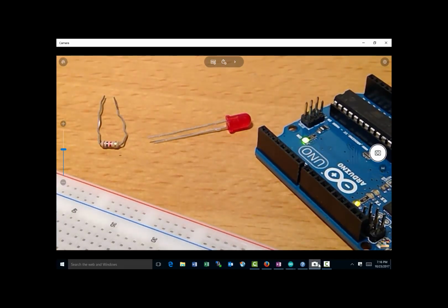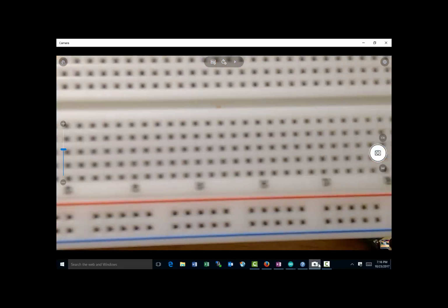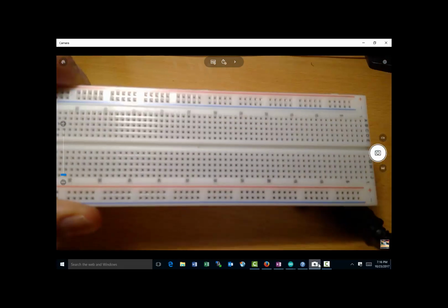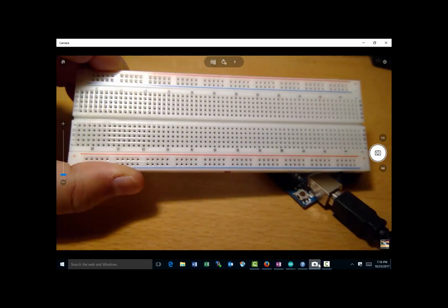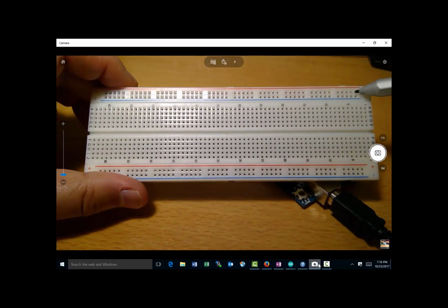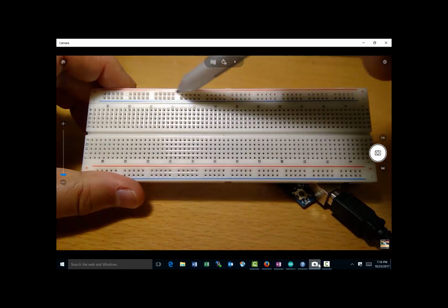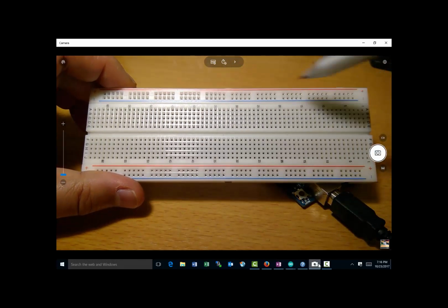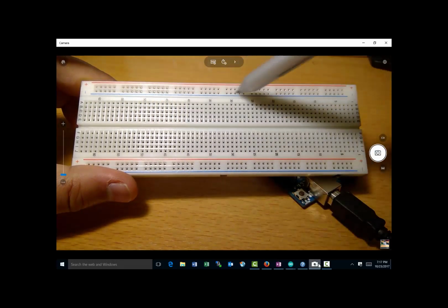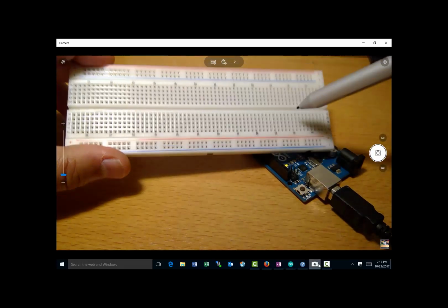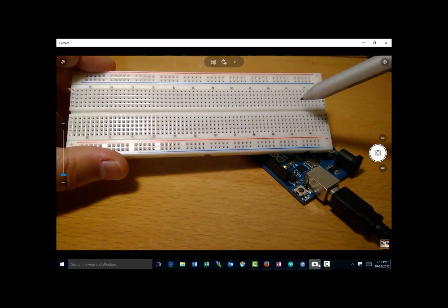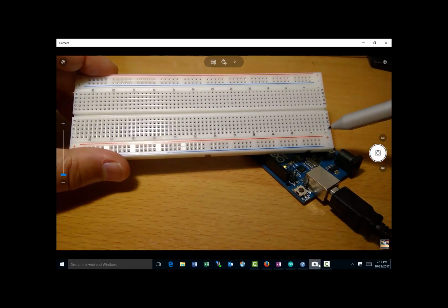When we want to build a circuit, it's really nice to be able to connect things and disconnect them without having to solder or jumper things. So this board is very useful if you've not seen it before. This is called a Protoboard. All of this row is completely connected to each other from one end to the other end. Blue is connected all together, but not to red. Same thing on the other side. And each of these 5 holes are connected to each other.